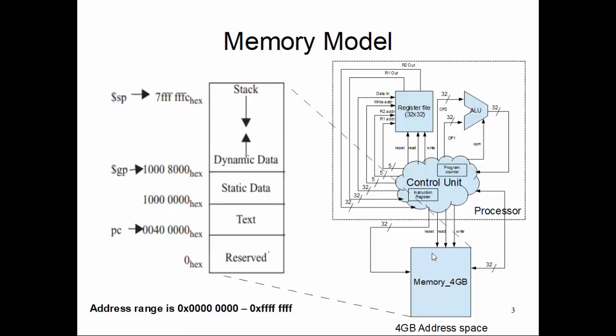So we have some usage guidelines. This is a pure convention, a software writing convention. It's not imposed by the hardware. For example, the convention says that from address 10010000 till 7FFFFFFC, we need to use it as stack or dynamic data, like heap data. And the addresses from 0 up to before 00400000 are reserved, we cannot write there.